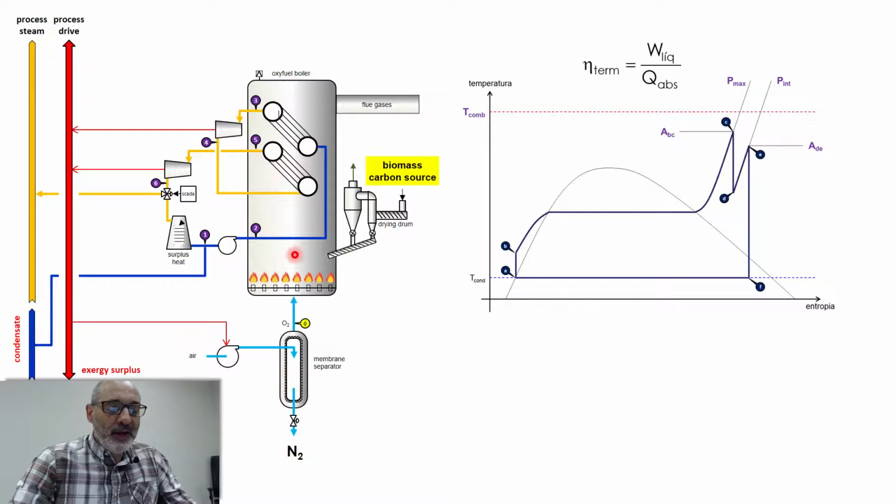Okay, so you burn biomass with pure oxygen, that you extract from air. So this diagram actually represents more or less the physical installation. So this is a compressor. It's getting air, compressing, and passing this compressed air through a membrane separator. So you get oxygen on the outside and nitrogen here. Okay, so this is a new and efficient separation technology.